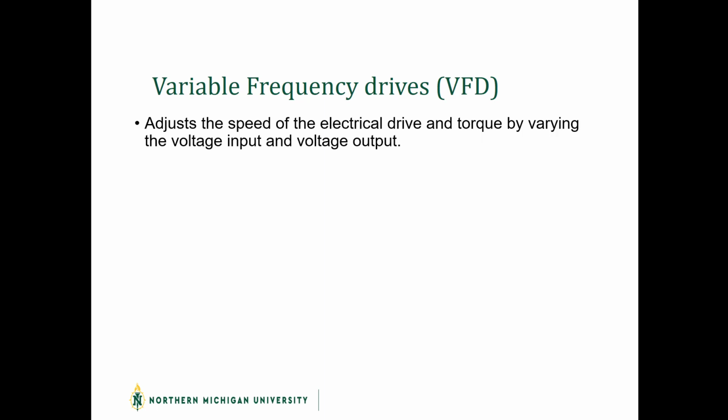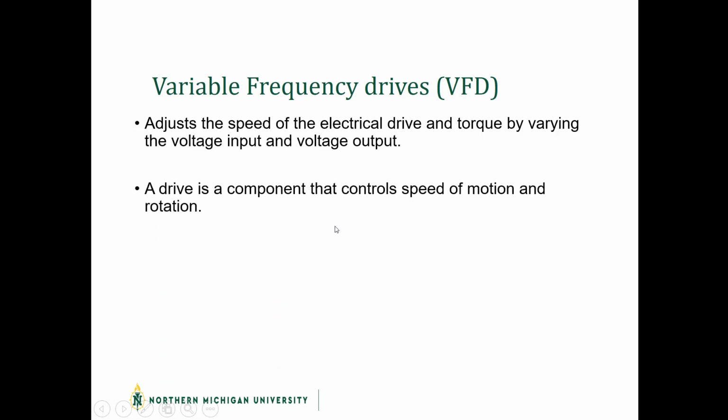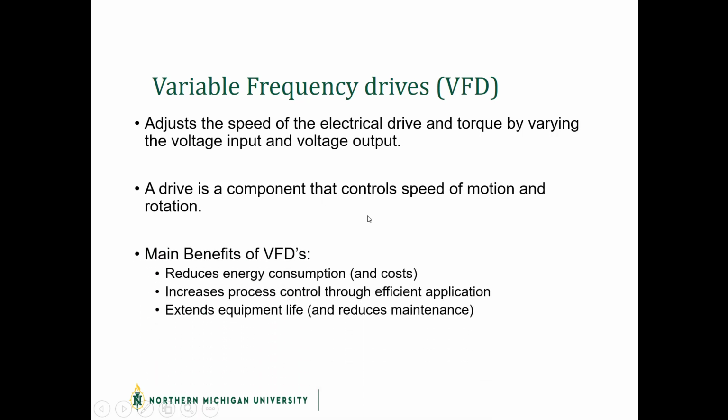I throw it in here because it is talking about voltage, input, output, and electricity. A drive is a component that controls speed of motion and rotation. So the main benefits of having a VFD are that it reduces energy consumption and cost, it increases process control throughout efficient applications, and it extends equipment life and reduces maintenance needs.